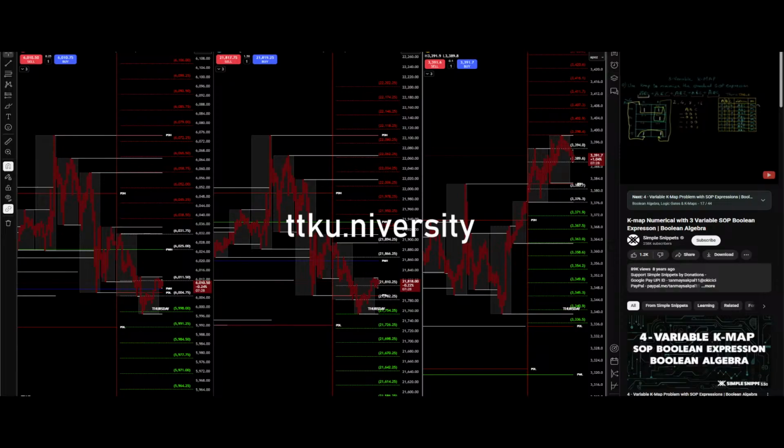As you can see, the value of B remains 0 throughout these different records. So I write it separately, and since it is a 0, I write a complement over here. So this is the output for this group. That is, if you simplify these 4 terms associated with these cells, you will be left with the answer B complement.